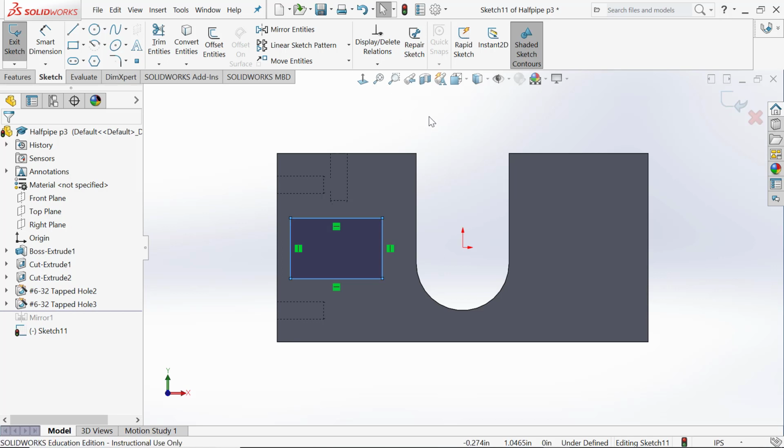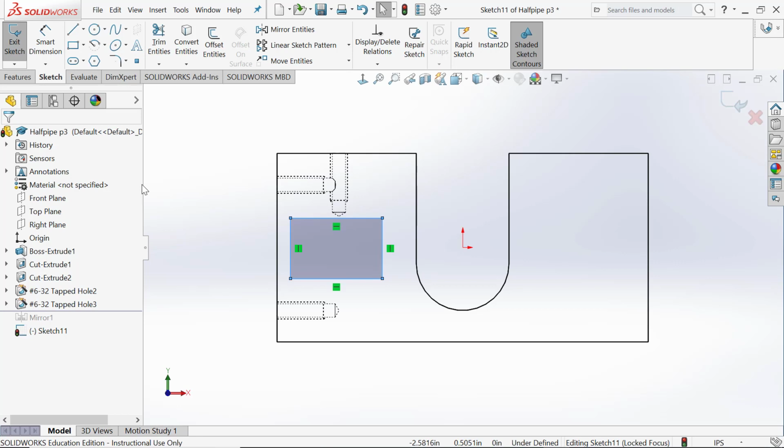So we would need to be able to see where those screw holes are. Now you can kind of see them in mine. Yours might not even be showing those, but there's a way to be sure you're seeing hidden lines such as those. And that's to go to the top up here under the display style option, so it's the second cube, the cube next to the eyeball. Click the down arrow next to that and choose the second one from the bottom, which is hidden lines visible. It sort of makes your part transparent, like it was made out of plastic or glass or something. And now you can actually see precisely where those holes from the threaded holes go in this part, and it'll allow you, while you're crafting a part, to prevent something from running into something else.